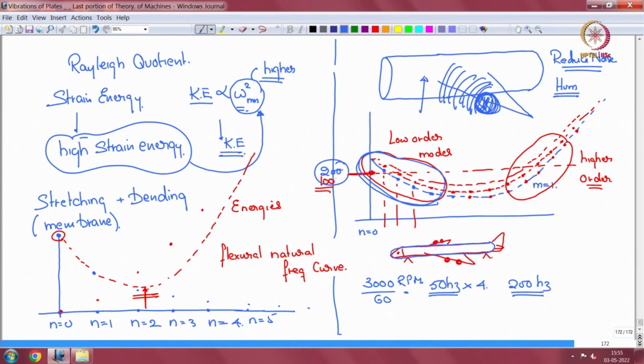Okay. So now around 200 hertz there are that many modes. You could have 100 modes. So that many modes are now responsible for transmitting. That means the shell vibrates. This is shell vibrations, and the vibrations in turn send sound inside the cabin.